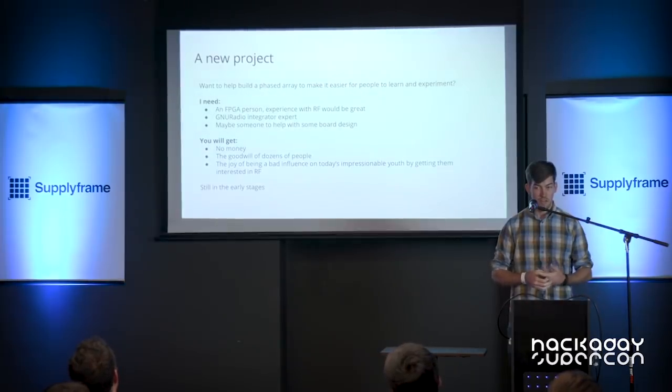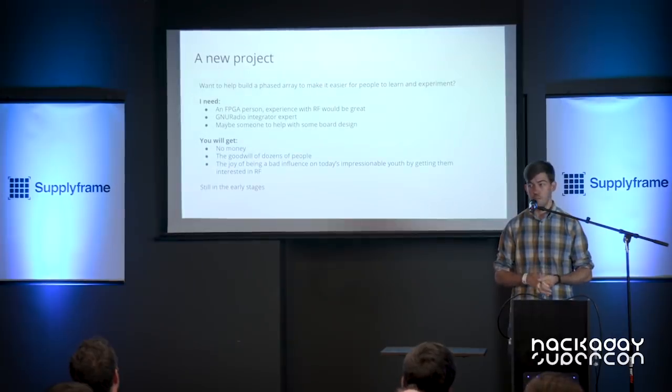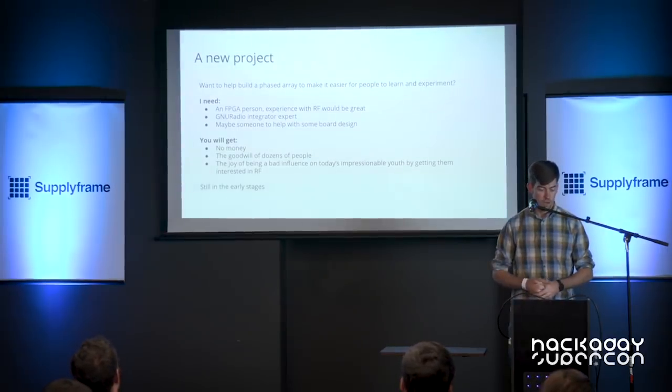The one that I found is actually quite cheap in single quantity. Like I said, it was not designed for this at all. It was designed for communication over short distances. And it's 60 gigahertz, which is very high frequency and would be effectively impossible to prototype at home unless you were willing to spend at least several $1,000s on stuff on eBay to do testing for that. SMA doesn't work at 60 gigahertz. Even the connectors you need are crazy expensive.